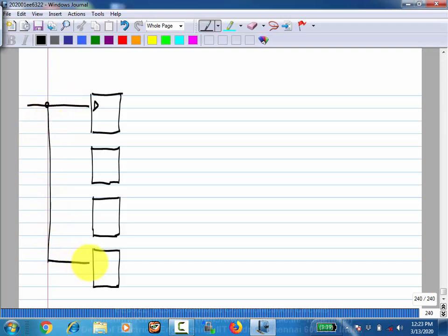So you sample the input data with 4 flip-flops now, and I'll show all of them with rising edges but with different clock phases. Okay.